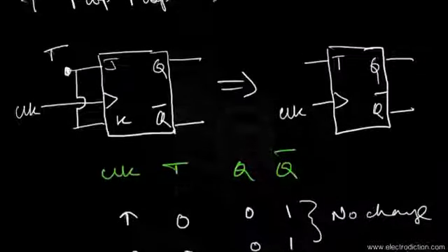Now, having said that about the T flip-flop, let's move on to the next type of flip-flop that can be derived from the JK flip-flop. Here we have the D flip-flop that I was going to tell you about previously. Let's consider this box as the logic diagram of a JK flip-flop, which I am doing just to save a bit of time and space. So here's the JK flip-flop, and there's the clock input. In all cases we assume a positive edge triggered JK flip-flop for simplicity.